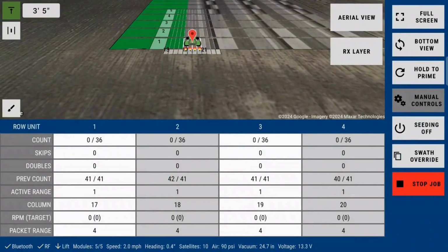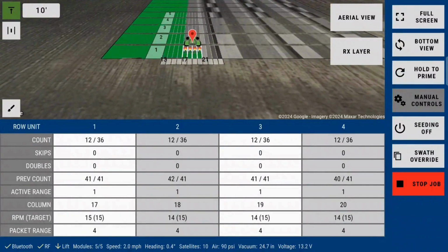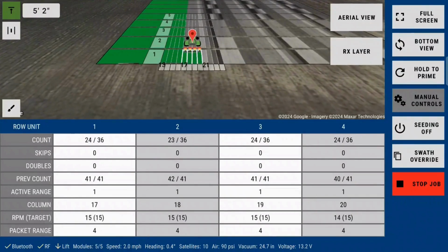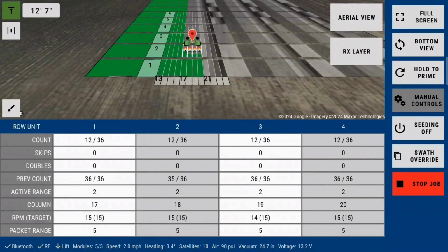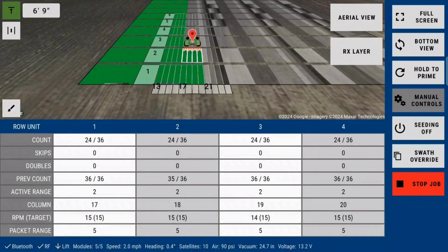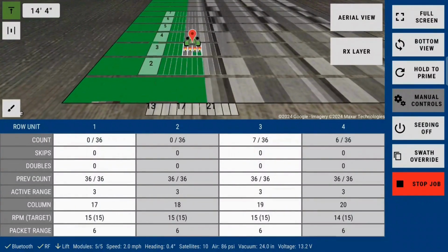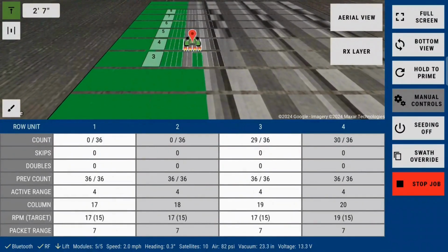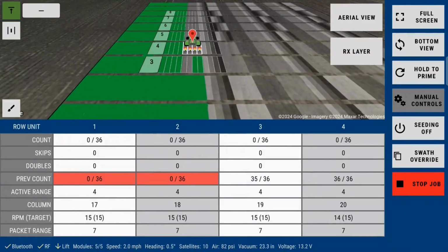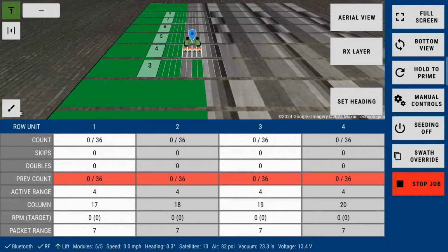In this example, we'll go through what may happen if someone were to miss a packet in the field. SeedPro Elite has built-in tools to help make error recovery easier compared to our previous SeedPro 360 model. Imagine we were halfway through the pass and the operator missed a packet intended for the left splitter. In this example, we will stop pouring and plant until we run out of seed. We will then pick up and back up behind the affected plot.